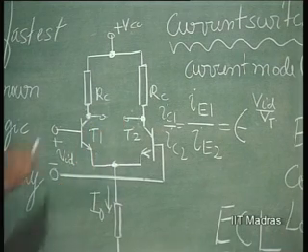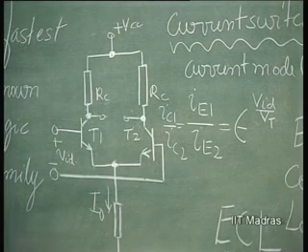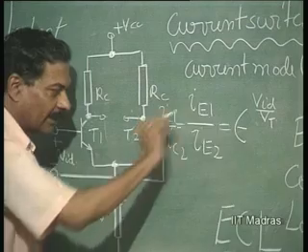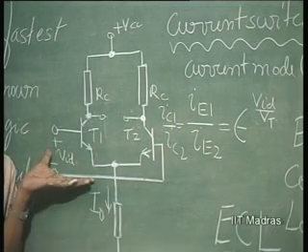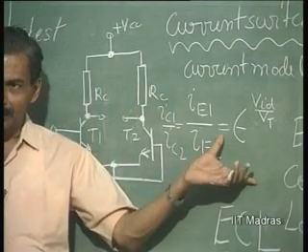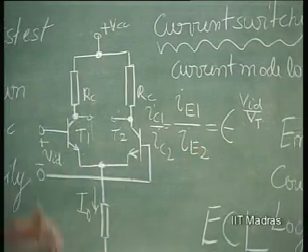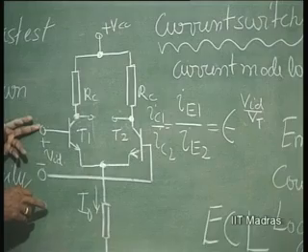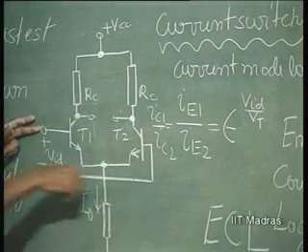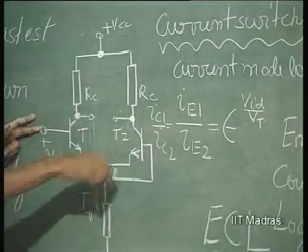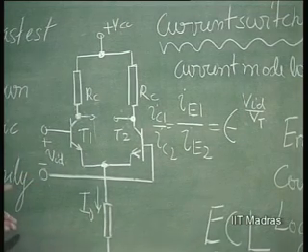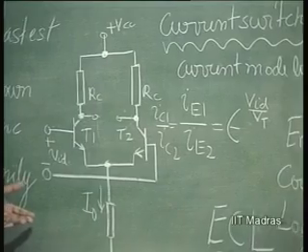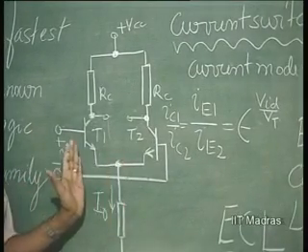However, if you connect an identical differential amplifier as its output, this is again connected, normally that is the state of most of the logic circuit. This logic circuit will be further connected to another logic circuit. So, the extent of voltage variation will get limited just like this happening at the input. At the input, we need only a change in voltage of the order of few tens of millivolts to switch the current from one transistor to other.